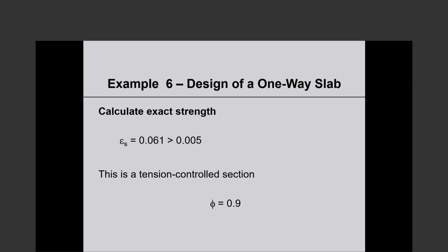If we use 3000 psi concrete with 72.5 grade deformed bar, is it allowed? Are you aware of anything like that, BNBC? Say that again, what's the question? Is 3000 psi concrete allowed with 72.5 grade deformed bar?